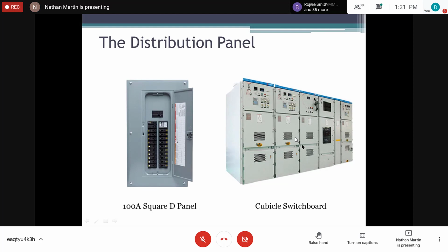Now, this is our standing cubicle switchgear, and inside these switchgears are bus bars. The cables will come into the top of the switchgear and go to the different circuits, right? For this switchgear, your main disconnect is shown right here, which disconnects all of the different cubicles. Once you switch this to the off position, all these cubicles will go down, right?